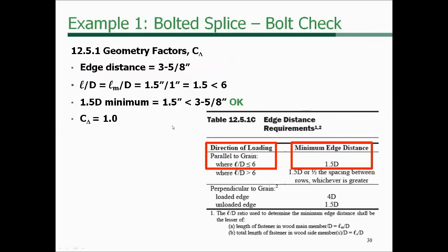So the geometry factors then account for edge distance requirements, end distance requirements, spacing. The edge distance in our case is 3 5/8.